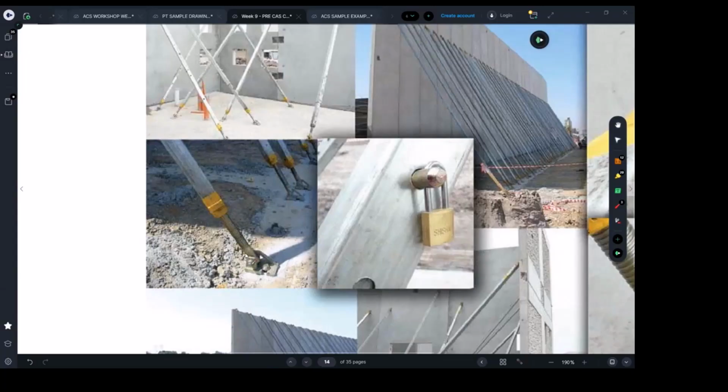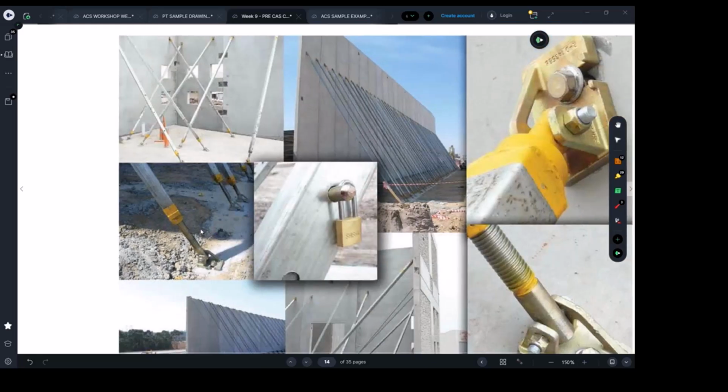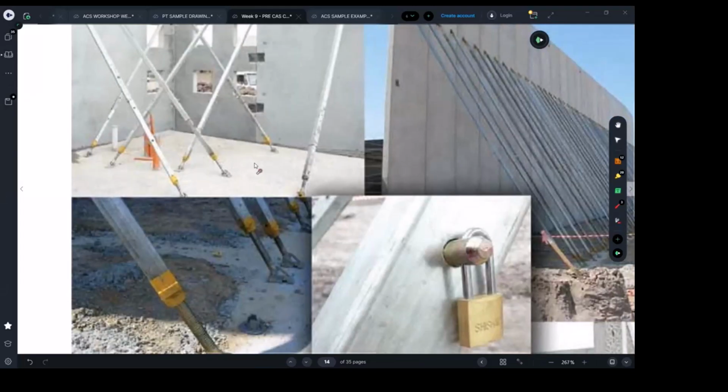They may only be mass concrete, just pouring concrete there, 600 by 400 wide, just to temporarily take the wind load. And then you will just keep it under the ground. And then you're going to cover it with soil or cover it with a slab, a properly finished slab. So there are different thoughts that need to be considered at the base of those props.